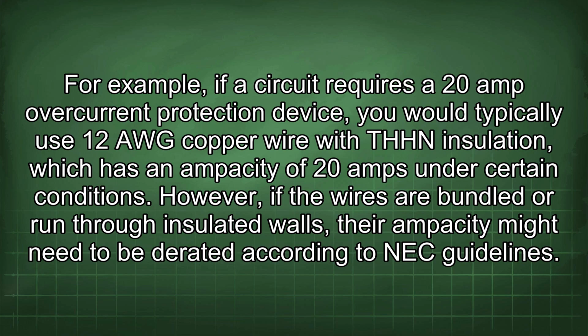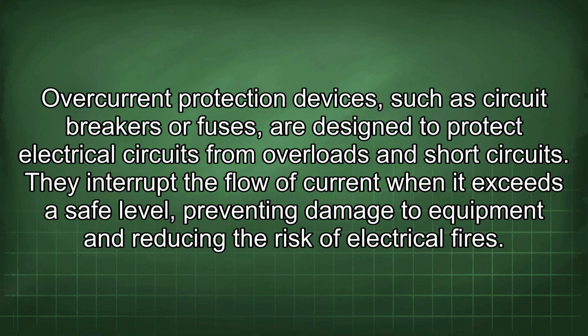NEC guidelines. Overcurrent protection devices, such as circuit breakers or fuses, are designed to protect electrical circuits from overloads and short circuits. They interrupt the flow of current when it exceeds a safe level, preventing damage to equipment and reducing the risk of electrical fires.